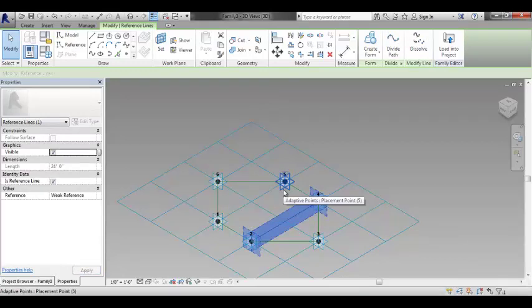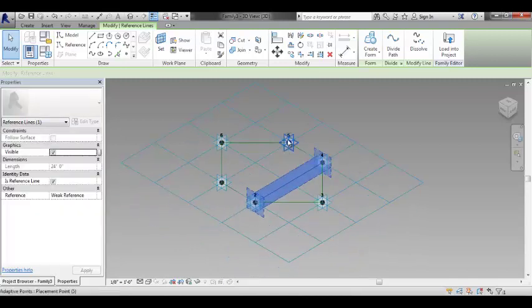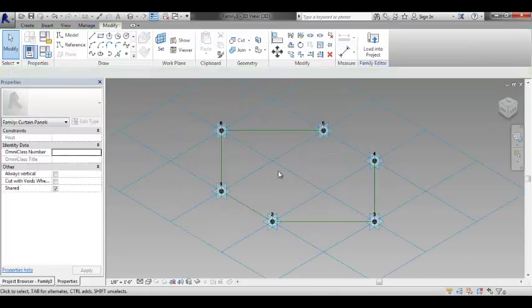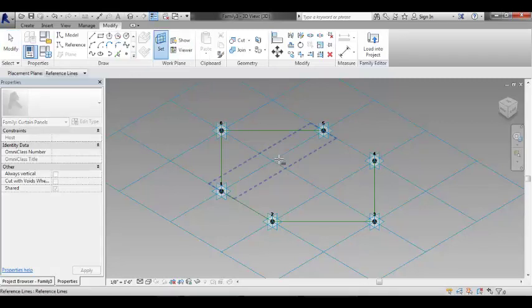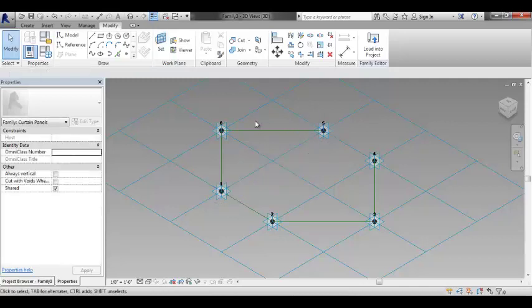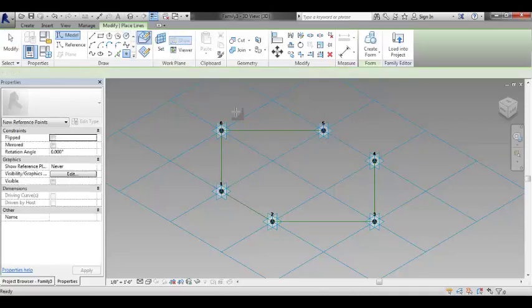So the next thing is that gives me an ability to put, at least get center lines for each one of these. So I want to put in 2 lines going in the vertical direction. Now that's not easy to do in the 3-dimensional view. I'm going to try and build this whole entire thing in this 3-dimensional view, because really I want to start getting into that mentality. So first is I'm going to set my work plane. And on that line, I can tab through, and it's got 2 separate work planes associated with it. So I'll pick the one that goes vertical, and then I'm going to set a point at the midpoint of that line.